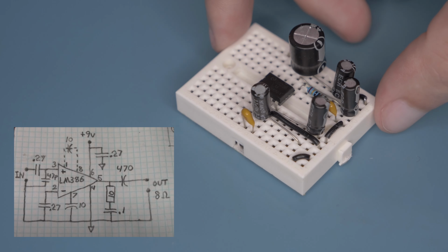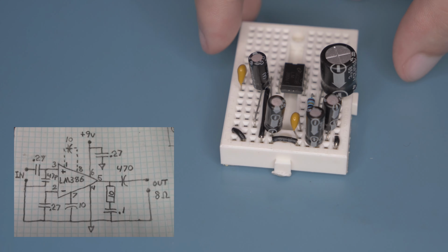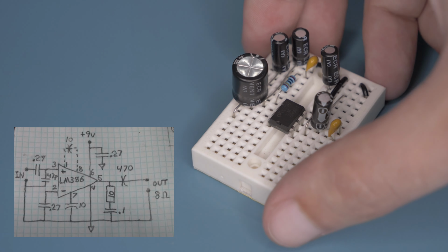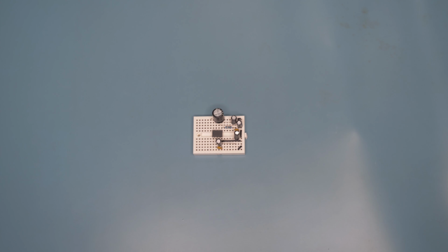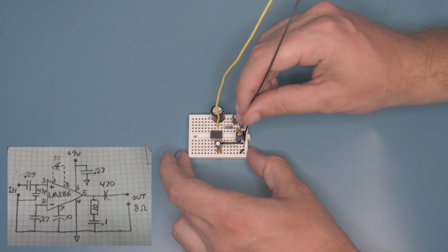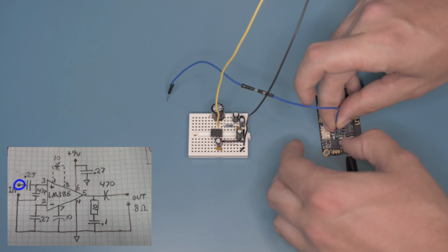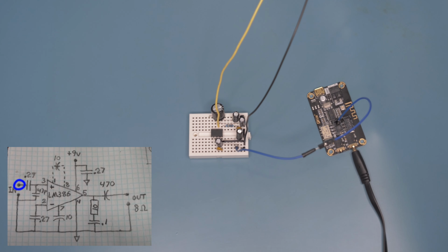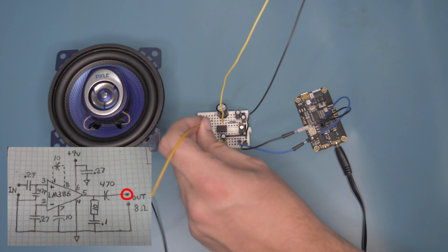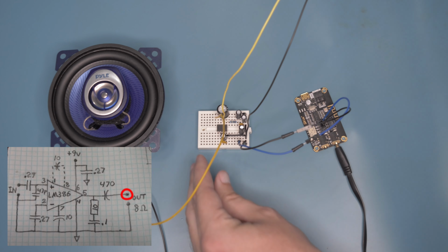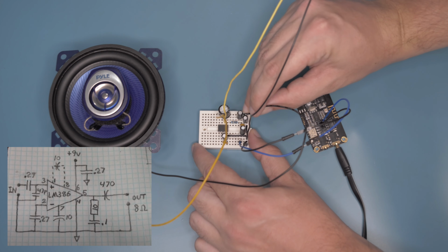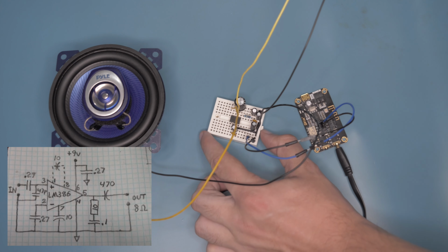After putting together the circuit, we have 3 things to connect to it. The power source, which will be 5 volts for now, the Drok receiver, and the speaker itself. All 3 need to be grounded together. The power source connects here to pin 6. The left or right channel from the Drok receiver will connect here, before the capacitor to pin 3. And lastly, the positive line of the speaker goes here, after pin 5 and a 470 microfarad AC decoupling capacitor. I'm pretty sure this capacitor is here to block any DC voltage from getting to the speakers. For simplicity, I'm just going to use one of the audio channels for now.